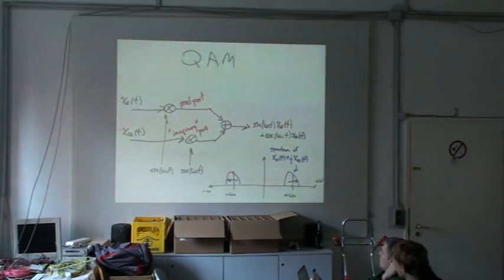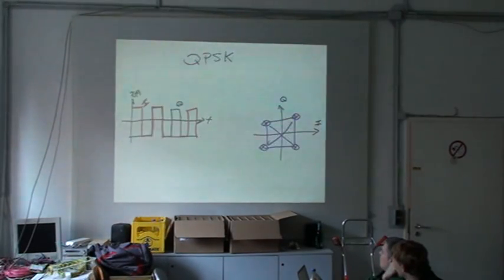The signal that's coming out of here is a real valued signal, because you can't have two voltages on a wire at the same time, but the properties are such that it appears that what you did was you took a complex valued signal and applied amplitude modulation to it, and you ended up with spectra that are no longer symmetric about the carrier. And all modern communication systems operate that way.